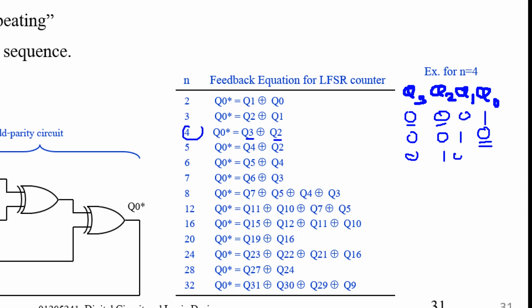Shift left. And then this is the same, so it becomes 0 right here. For the next one, copy this 3 bit, shift left. And it's different, so 1 right here. Okay. If it's the same, Q0 becomes 0. If different, Q0 becomes 1.